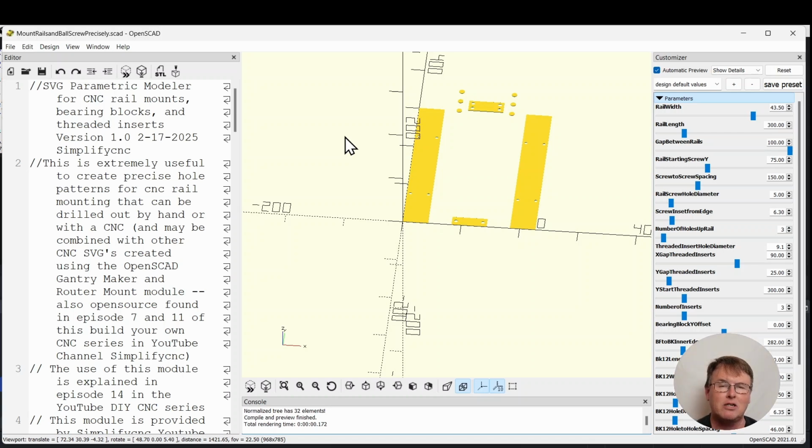Once you have that, also realize you can change the hole diameters. So they're little pinpoints. The holes will still stay centered the way I wrote the program. So if you want little pinpoints, you can put brad point bits down when you're drilling it out, especially if you're using a drill press or hand drill. That can actually be more valuable.